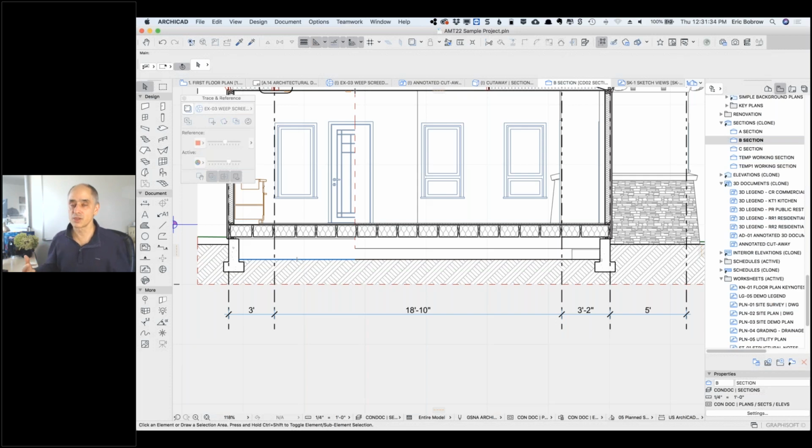Now, hotlink modules traditionally are used to bring in a building or two or three buildings into a site, and each one of them is linked to an external file, or to bring in a room or a suite or an office layout into a project and then repeat it n times, or to bring in one story and repeat it a bunch of times. Modules are used for all sorts of different repetitive things and for referencing. You can literally just select it and delete it, and it goes out of the project. But I've found that although the file is larger than you would expect when you start a fresh project, it doesn't get in the way with current computer technology.